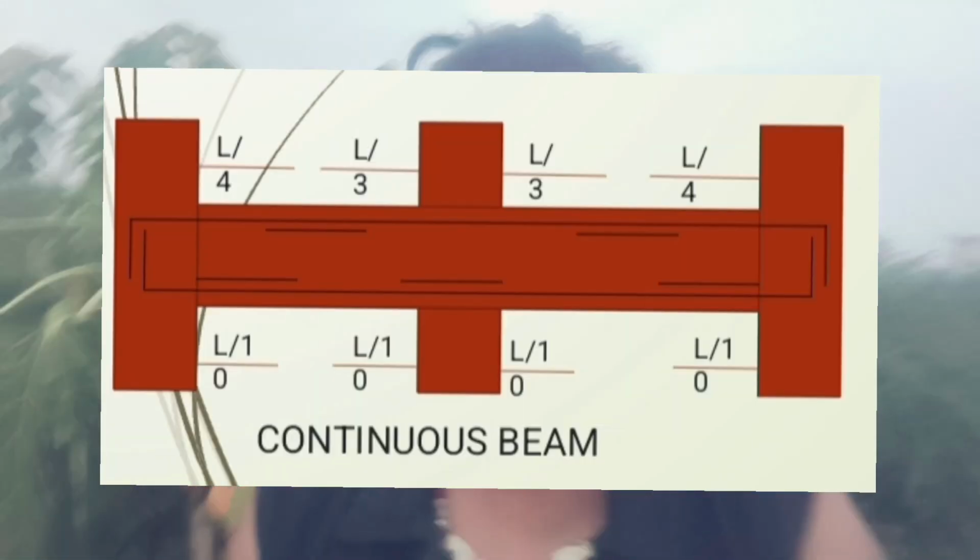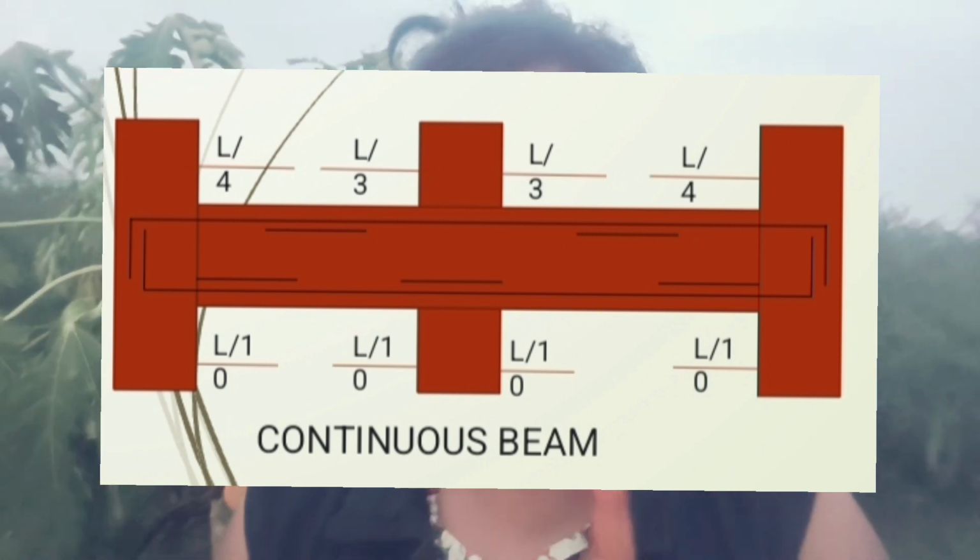What we have discussed is that there is some length they ask us to follow. For example, the 0.3 into L we discussed for the lap, the same length we use in the beam also. So in between that length we need to lap the top layers. And what about the bottom layer that we are going to discuss? Near the support is where we need to lap.